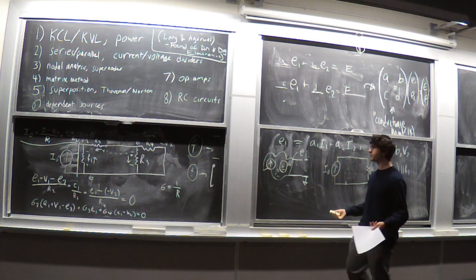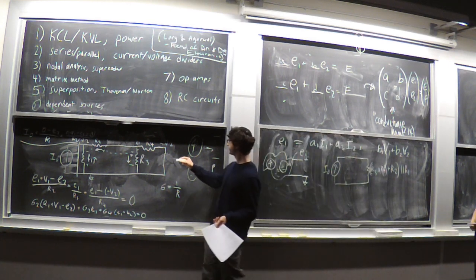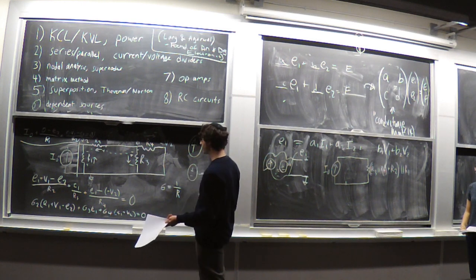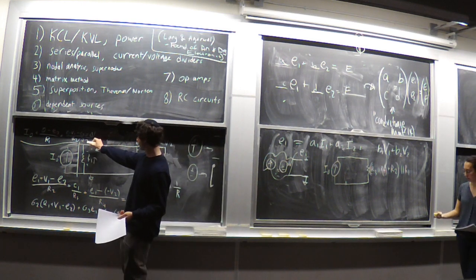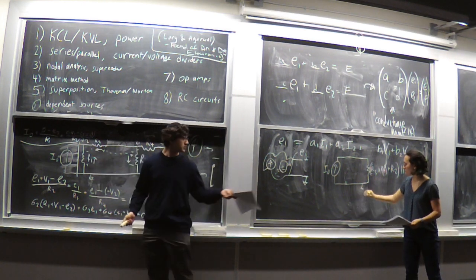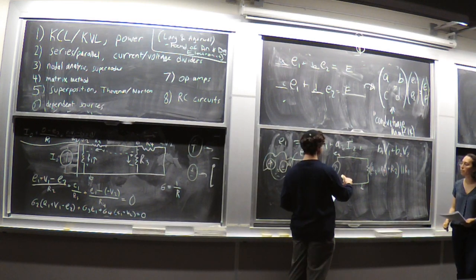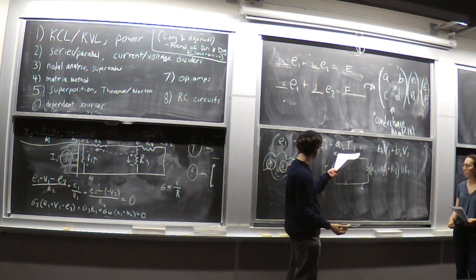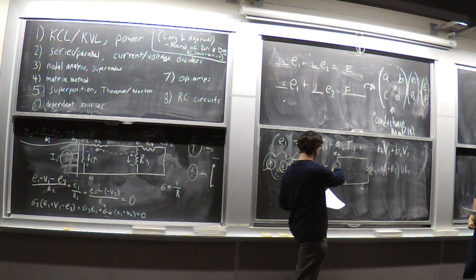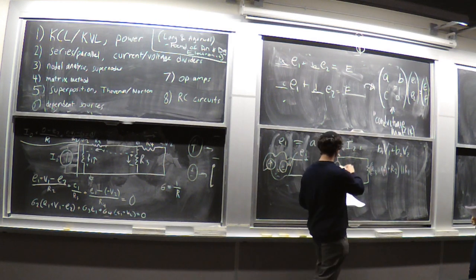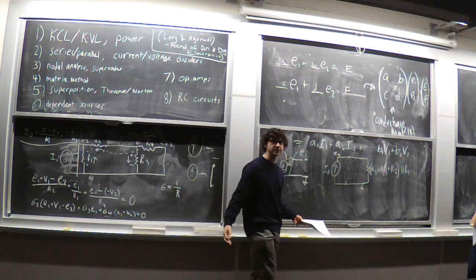So like, for example, if we were solving for some specific spot in the circuit as our output voltage, like if we were solving for E2, say, E2 stayed put. E2 is still at the top of this current source, and so now it would be pretty easy to figure out what E2 is. We have this current I0 flowing through this single resistor, quote unquote, and so the voltage is just I0 times that mess of a resistance.